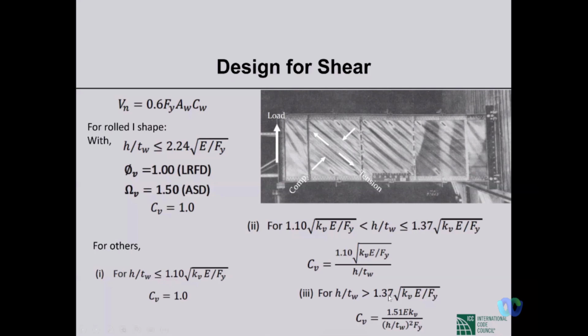We understand very well when you see this picture that there is a beam with stiffeners and a very thin web. Now, if this beam is applied with a vertical load, a lateral load transverse to the longitudinal direction of the beam, that causes shear. So it's kind of panel shear we can see in between the stiffeners.